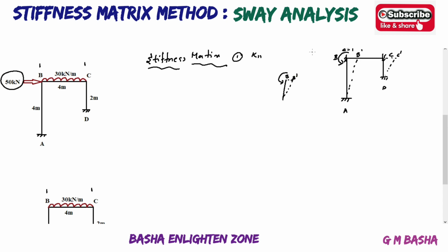So this is one unit, which is 6EI delta by L square. Whatever force acts here, the same force will be applied here also, which is 6EI delta by L square. Similarly, if you see here, the frame leads to sway like this, towards the right.